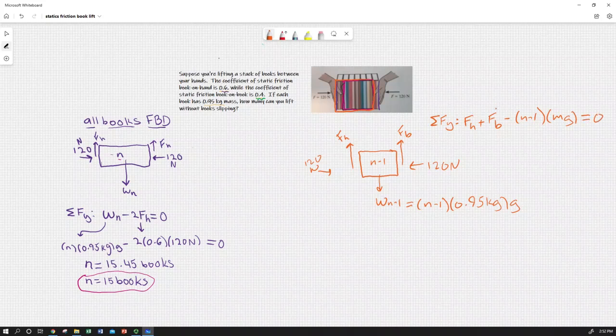When I apply imminent slip, I'm going to get a value for this one. This will end up being, this is limiting. So I'll say, okay, you can only get this much, 120 newtons. The problem is you haven't really defined how much this one's giving you.